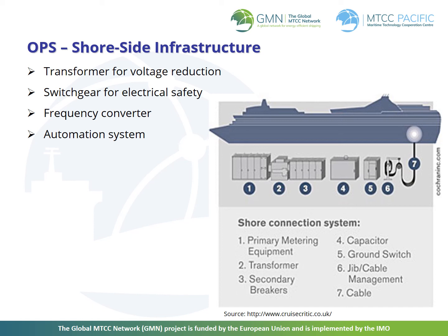Installing new shore power systems requires shoreside infrastructure and can be expensive. However, it can also result in major reductions in port emissions. The infrastructure is typically constituted of the following: power connection to utility, power transformation, conditioning and switching equipment, land for these facilities, cabling, synchronization equipment, and berth-side infrastructure.